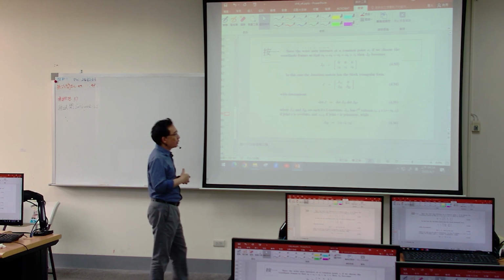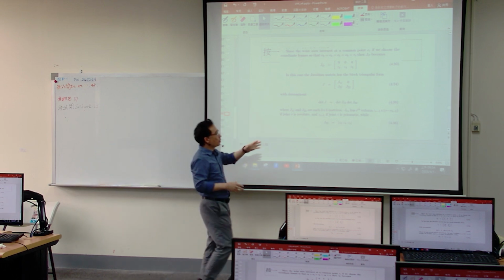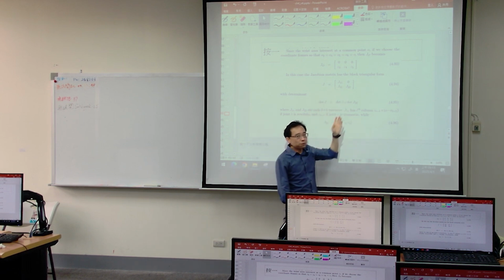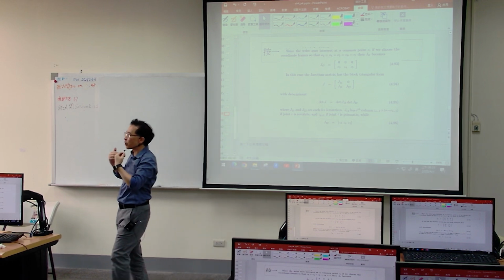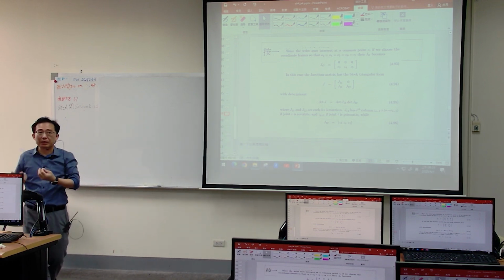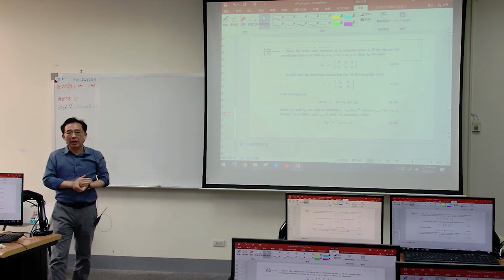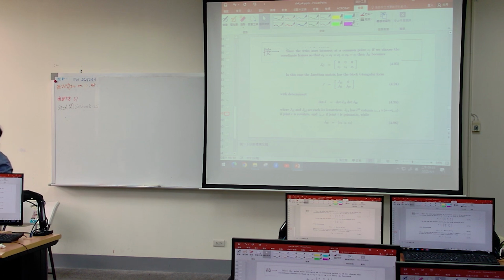But J is 3 by 3 and very complicated, so they have a technique. They say that for the orthogonal section, if it equals 0, then my determinant equals 0. It makes sense. So for the determinants J11 and J22, if either of them equals 0, then the singularity situation shows up.